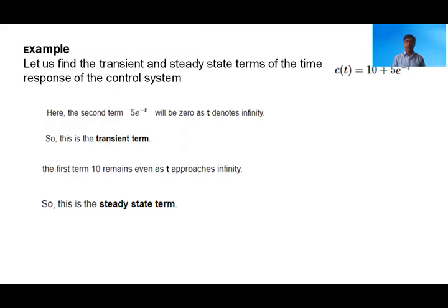It will take some time to reach its final value, and there it will stay constant. So any system in general will take some time to settle down. That's why when you analyze a system in the time domain, we need transient response analysis and steady state analysis. So we can discuss the transient behavior as well as the steady state behavior of a system.